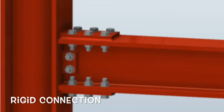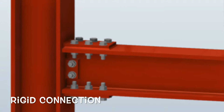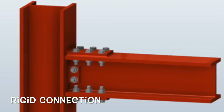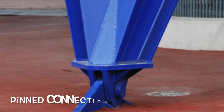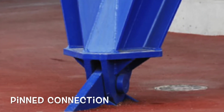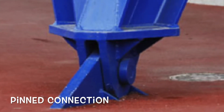Connections also play a big part in how the members react. Rigid or fixed connections are used in industrial buildings to resist or support vertical, horizontal, and rotational movements of the structure. This means that a structure needs at least one rigid connection to cover the moment of the structure. Pinned connections are the second most commonly used and strong connections seen on industrial buildings. They help resist the vertical and horizontal movements of a building. These can be used in all locations of an industrial building and, depending on its use, can look or be constructed differently.